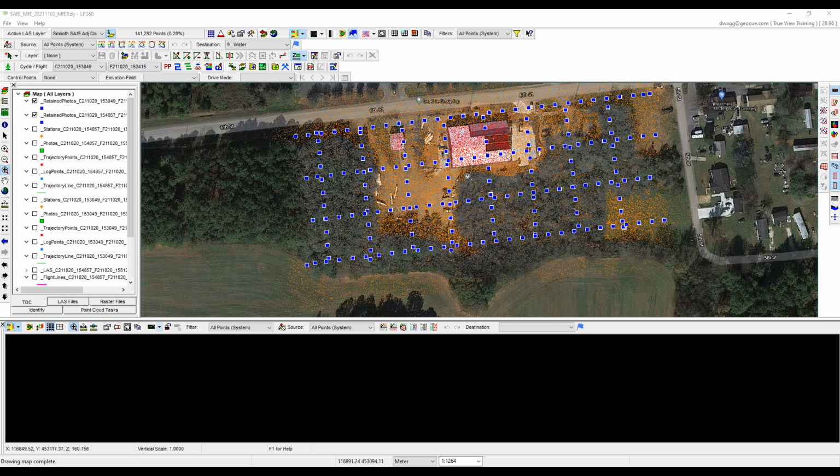It takes about a minute on a project on this, which would be about a cycle's worth of data. And then I've done some additional manual classification of the building surfaces, because I'll get a better looking ortho if I've done some other classification for those types of non-ground features such as buildings. We could go a step further and put some vector elements in here using some of the feature edit tools within EVO, and that would really give us some sharp edges around features. But this will be sufficient for a pretty quick ortho.